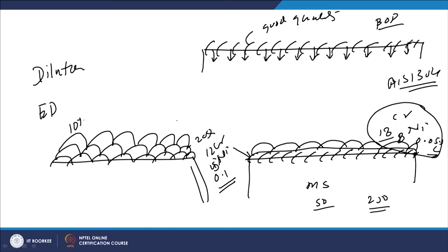So, the degradation in composition, or compositional modification due to the dilution, will be reducing as we keep on increasing the number of layers. But the first layer, of course, which directly mixes with the molten metal, its composition is most severely affected, and the maximum change in composition is experienced in that case.